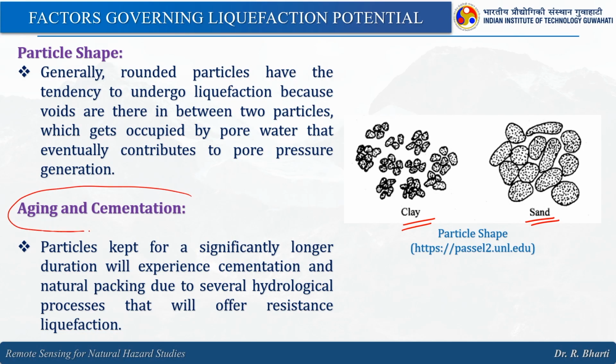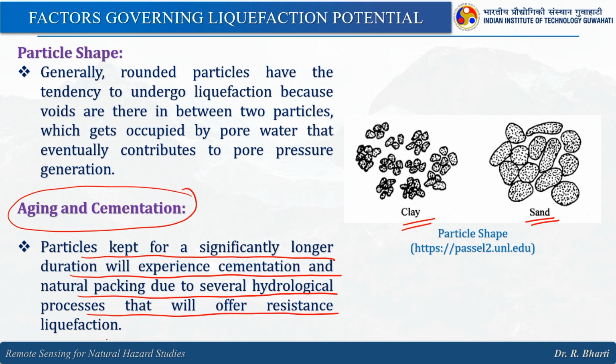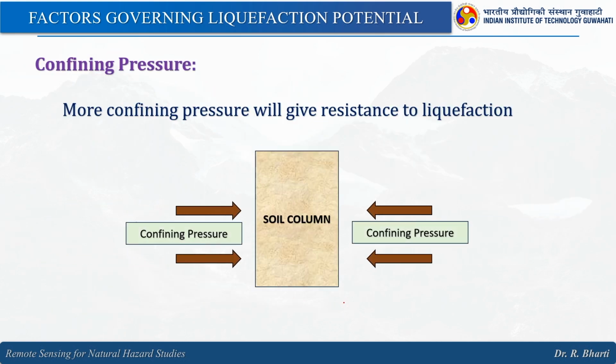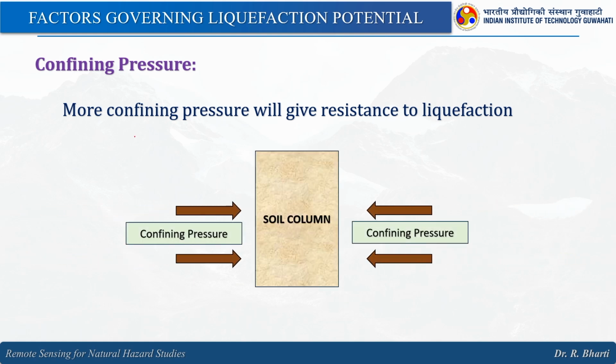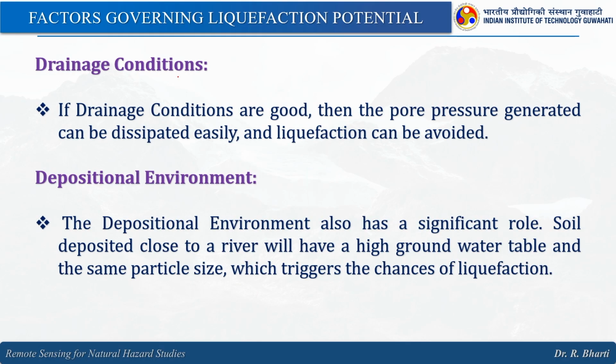Then aging and cementation. Particles kept for a significantly longer duration will experience cementation and natural packing due to several hydrological processes that will offer resistance to liquefaction. Then when we talk about the confining pressure, here you can see this particular animation, the more confining pressure will give resistance to liquefaction, because there will be no scope of dissipating the pressure, right. Then comes the drainage condition.